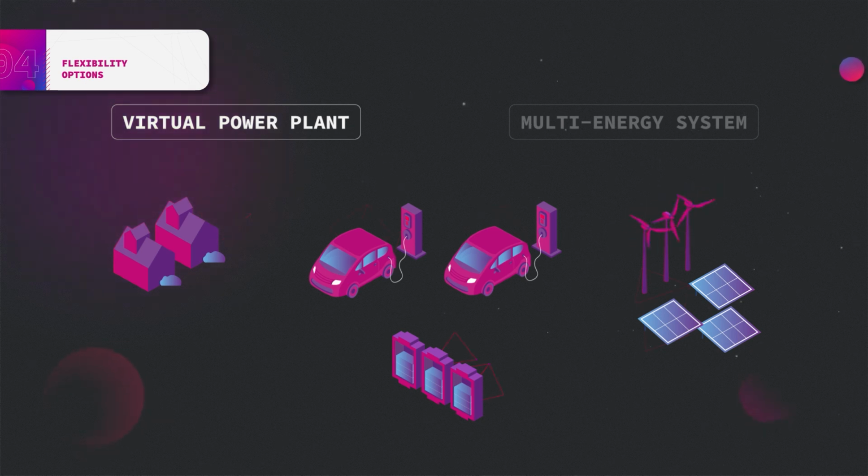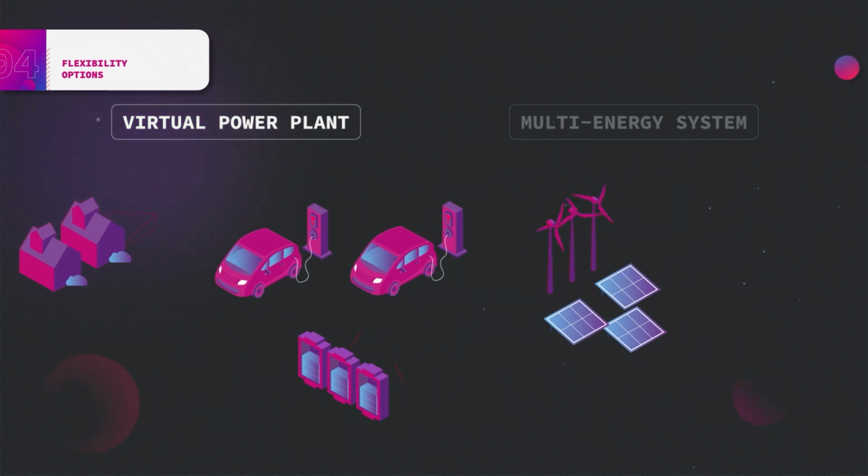The contracts with the distributed generators and the storage units cover the availability of the resource according to season and time of day, as well as the general energy and power controllability of the units. The contracts with the controllable loads may cover the availability of the loads based on location or time of day and the comfort level of each consumer. Comfort levels are, for instance, the upper and lower temperature limits of thermostatically controlled loads, defined by the consumer.